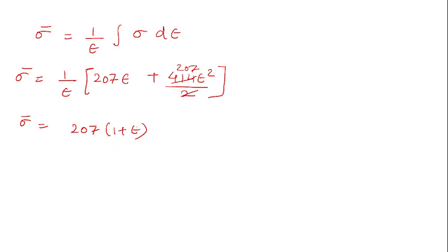Now, what will be your epsilon? Your epsilon will be true strain, so it will be ln of h0 divided by hf.